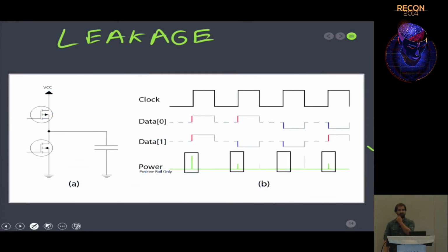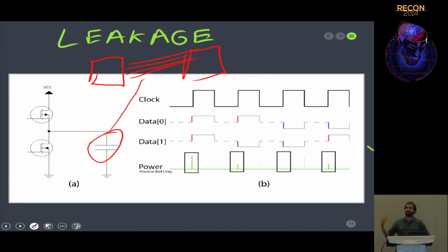So it uses this pretty basic idea, and that's that if we have a digital device, inside the digital device, aka a chip, there's going to be different modules. The ALU might go to registers or something like that, and in between them, there's the data bus that the data goes across. Each of those lines of the data bus is basically a capacitor that, to set it high or low, you're driving it to 1 or 0. So it takes physical electrons to do that, which means it takes power, which means that if you were to monitor the power on, say, the VCC line here, you could say, hey, at one instant in time, it took more power than at another instant in time, so it's probably setting more of those data lines high.